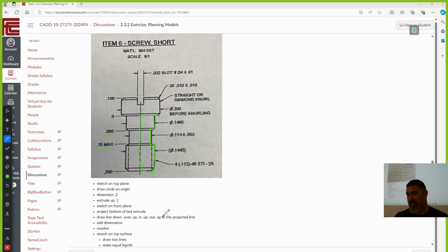On your lines, when you're drawing through there, you're including the chamfers? Nope, I'm drawing them sharp corners. Draw them sharp, because those are just chamfers. I have a good command. I can do all 3 of these chamfers at one time, right? 1, 2, 3, 4, 5. You should be able to do this. It says 3x, so that's this chamfer, and this chamfer. Okay. But there's little ones here and here too.